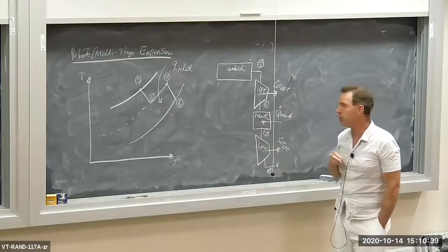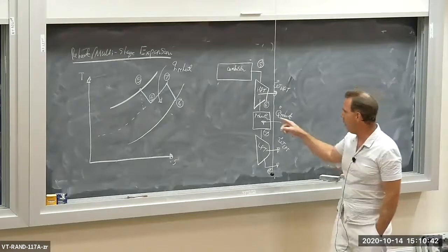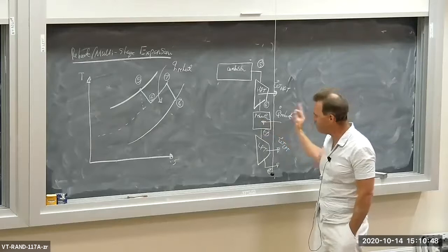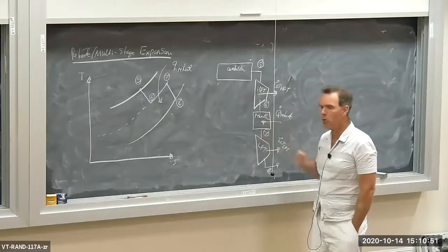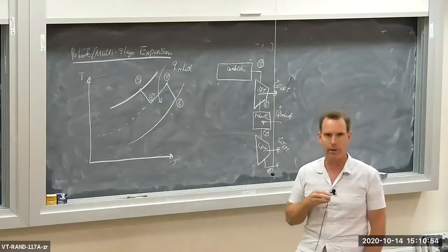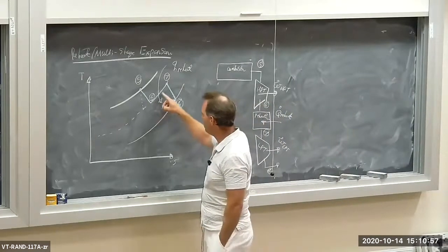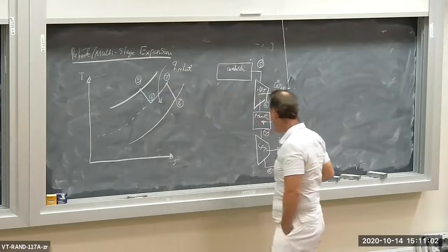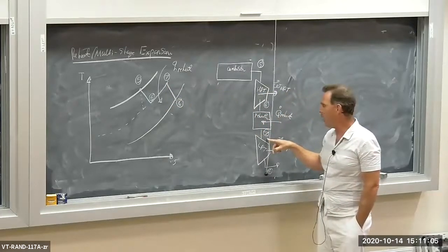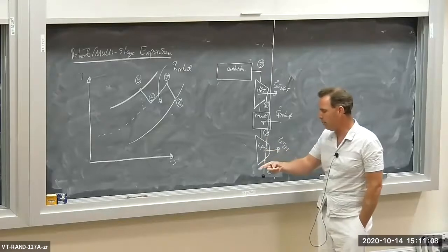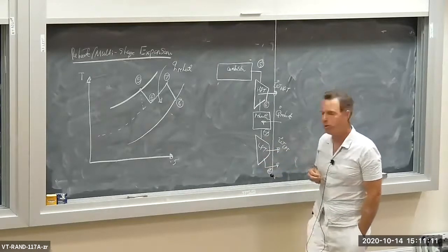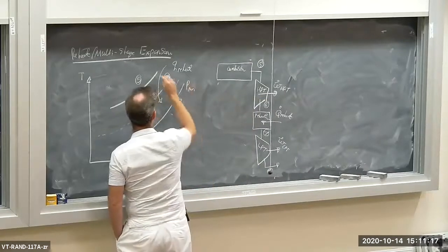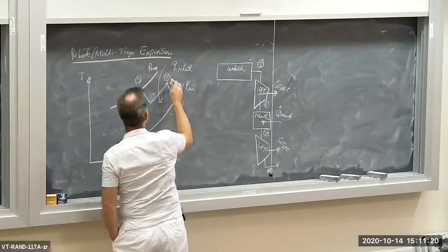Notice that these are irreversible devices here. Then, once we get to the outlet of the high pressure turbine, we reheat. We inject more fuel, and we burn more fuel in a combustion chamber called a reheater. So we add more fuel, temperature goes up, entropy goes up because we're releasing heat, and then we expand the now hotter air through a low pressure turbine until we get down to the minimum pressure. So we got P min here, and we got P max here, and we have some intermediate pressure in between.